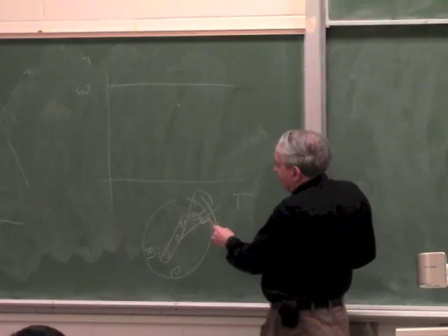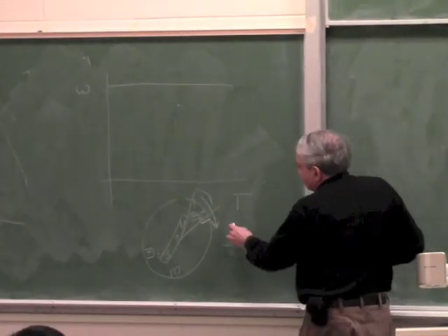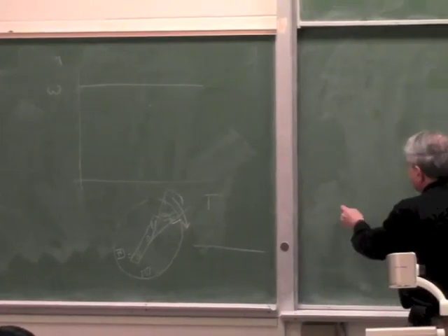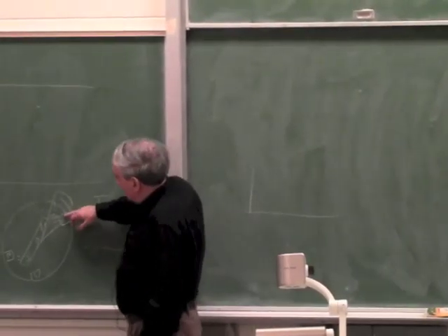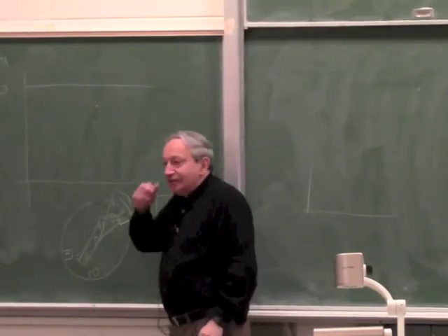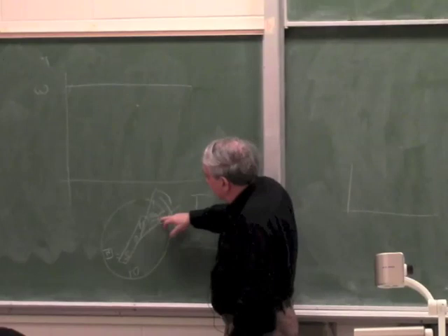So this power angle can only go up to 90 degrees and then becomes unstable. The reason is clear to everybody: if the power angle went to 180 degrees, the torque would be 0, because at 180 degrees, instead of attracting, it will repel.